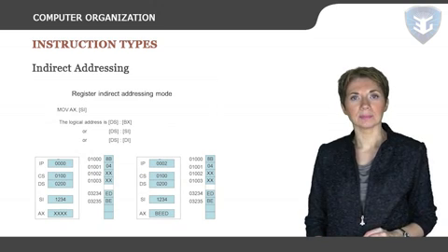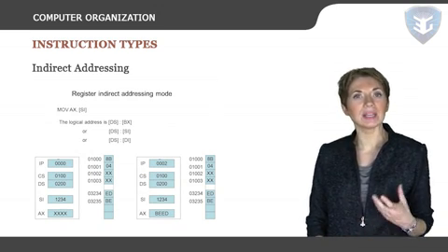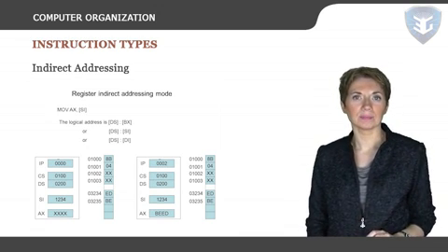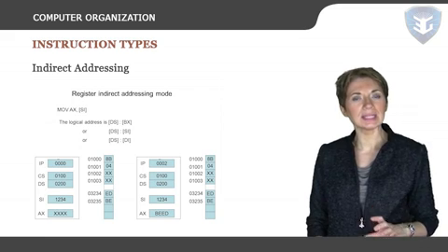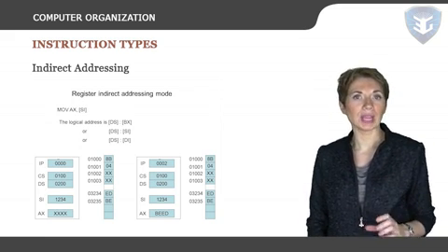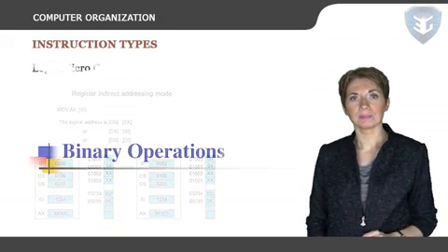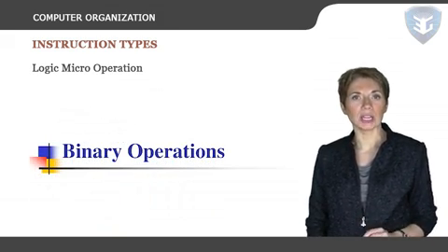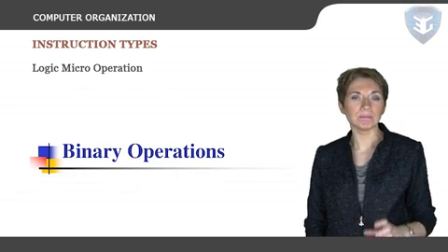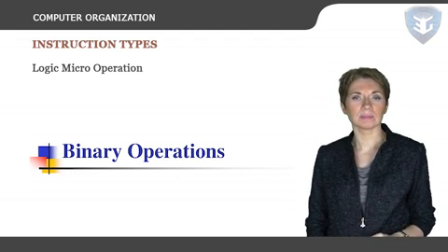Indirect addressing. When using indirect addressing, the operands give a location in memory similarly to direct addressing. However, rather than the data being at this location, there is instead another memory address given where the data actually is located.